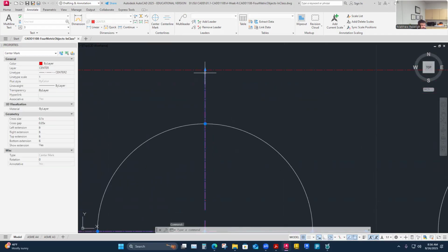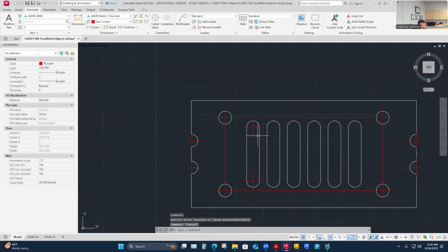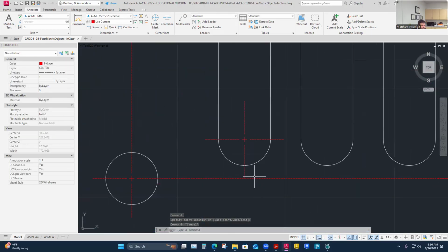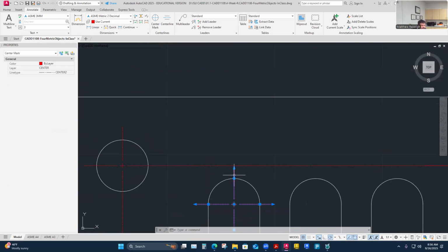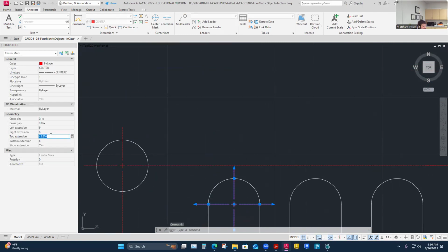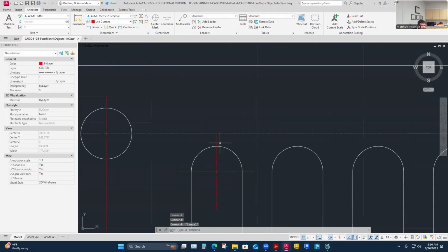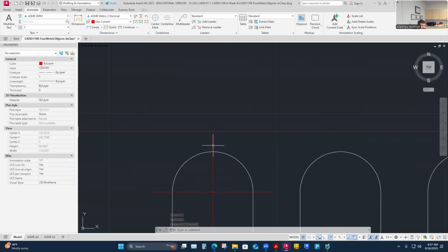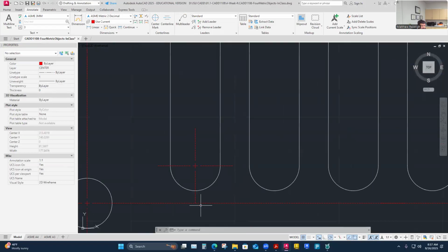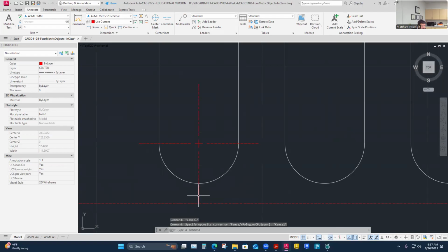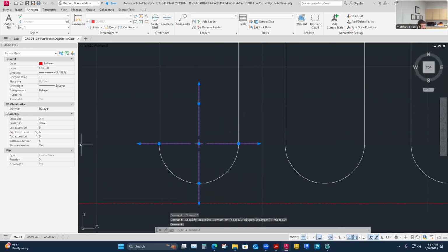This is the one that I have an option to either pull it a little longer or a little shorter. I probably will grab the extension grip on this. I know it's 6 how I set it, but maybe I'll just tuck it in ever so slightly to break up that alignment. You could do it by dimension too. I could have said that it's actually, what is it close to? A 5? Maybe I'll just say it's a 5 millimeter instead of 6 here. So I know the rule, but I've got to break it because I've got an alignment there. It wouldn't be the end of the world if I left it like this, but it's one of those small details that we talked about last week, and so that's the bottom extension that I need to be 5 in this case.